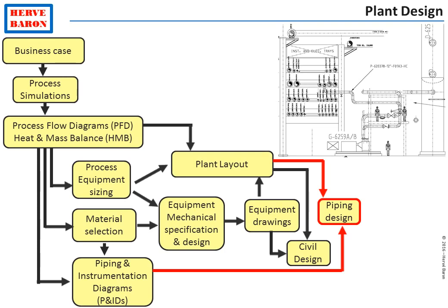It also involves calculations of lines subject to thermal expansion. Such calculations determine the requirement for expansion loops, and such expansion loops give rise to additional steel structures.